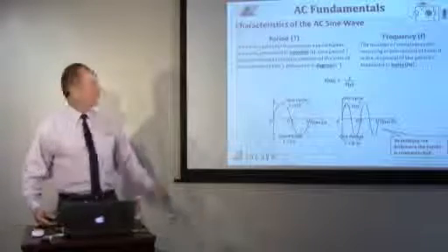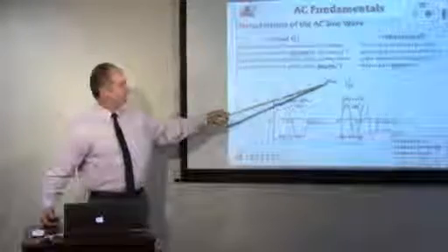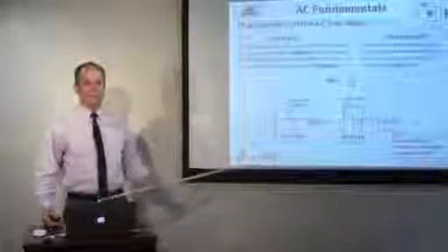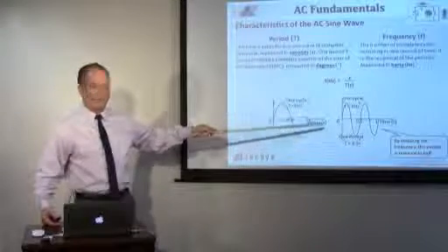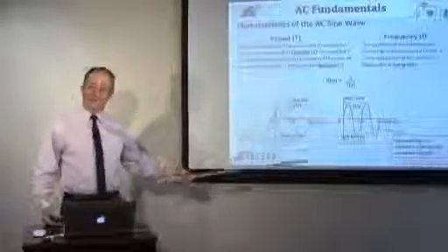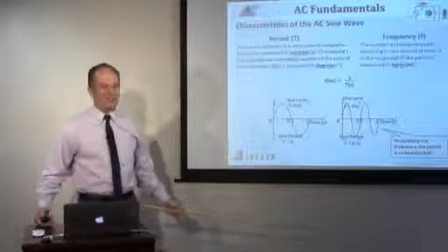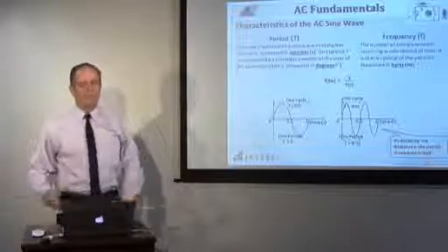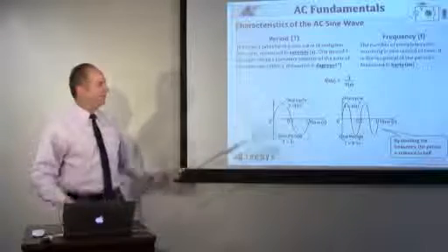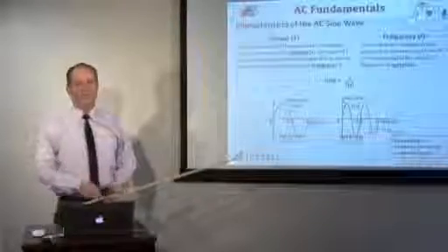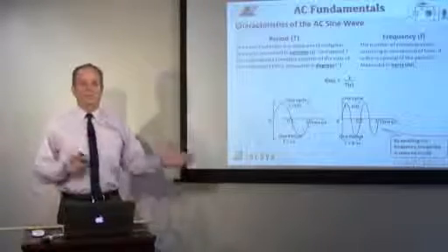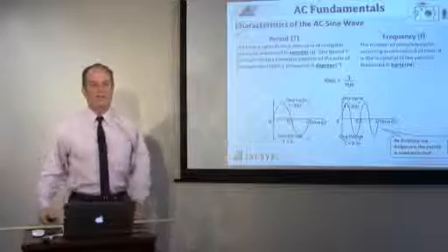And that little formula in the center that just popped up: the frequency is the inverse of time. Very true. If the frequency is so many cycles per second, then the time is so many seconds per cycle. Makes sense, okay? In radio and communications, you think of the frequency domain as being spectrum analyzers and the time domain being oscilloscopes. Depending on what you're looking at, frequency or time, you would use one or the other. Okay? So they're related like this.